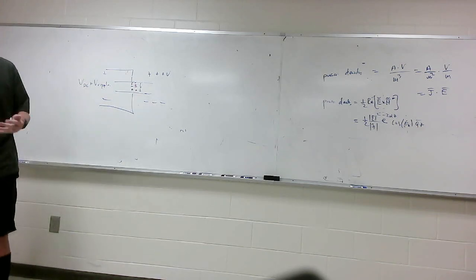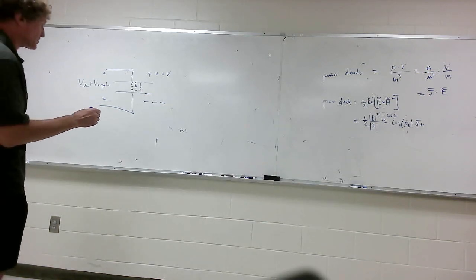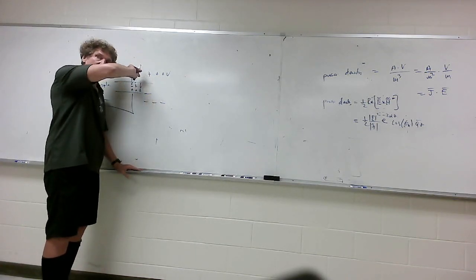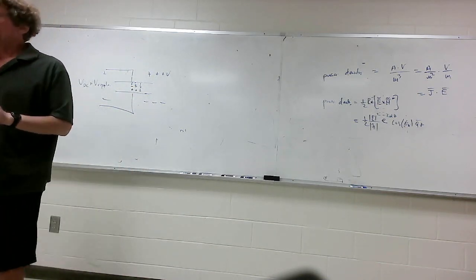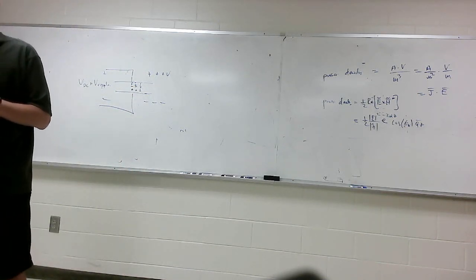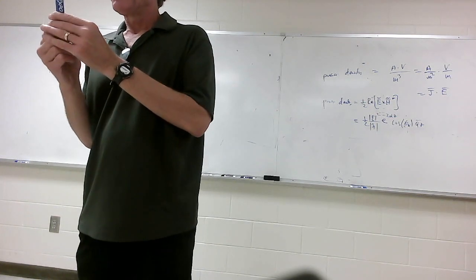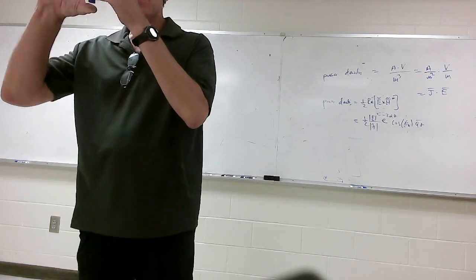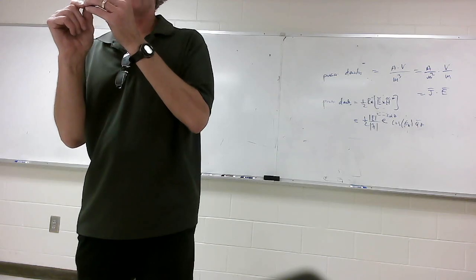Now, regular capacitors like mica capacitors, stuff like that, are different. Because it is a goo, these dipoles in an electrolytic will literally flip like this, and that's where you get a lot of thermal heating. It's frictional heating. But in a mica capacitor, in every other kind of capacitor that has a solid dielectric, those dipoles never move. Y'all follow me? They'll stretch, but they can't spin. They can't reorient. That's the problem. Well, that isn't a problem.